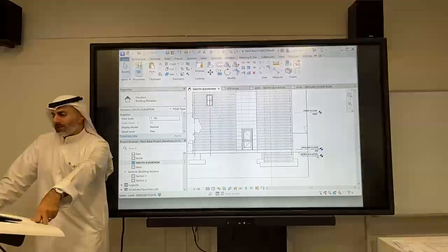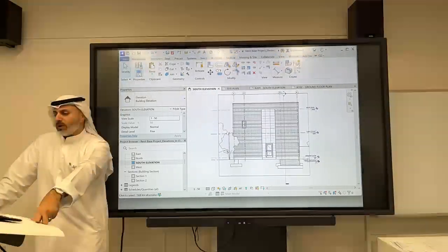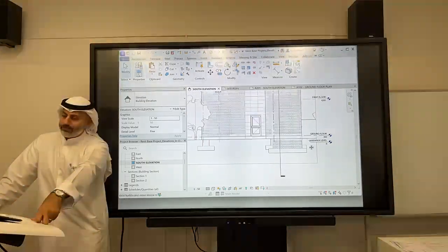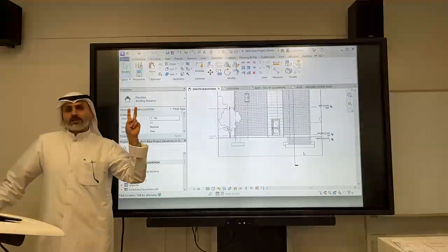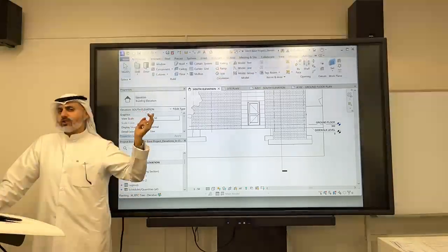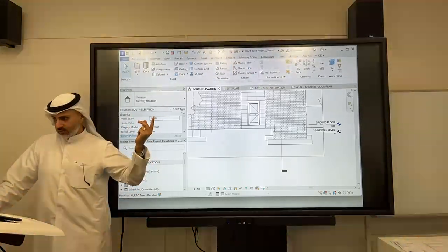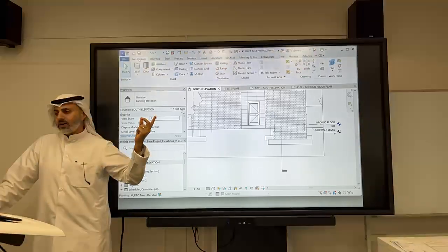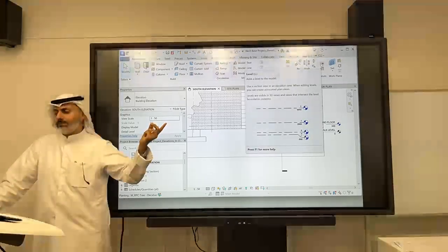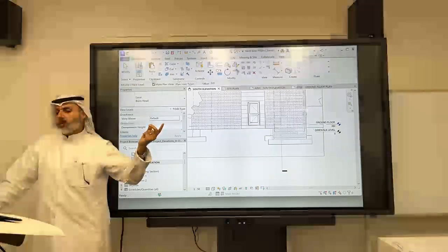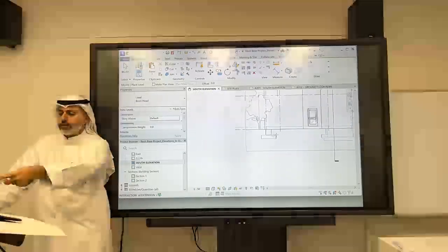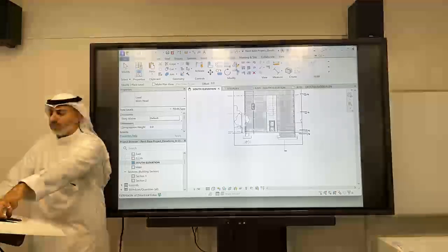Okay, so now we have ground, we have sidewalk level, first and roof. We want to add top and bottom of footing. So to add a level, there are 2 ways. One way, I'm just going to show it to you, but don't do it. There's a simpler way. You go to architecture and then it says level in here under data. Make a new plan or not, you check this make plan new or uncheck it. So that's one way, and then you can start drawing the level.